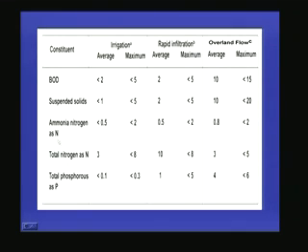The reason is, if you put wastewater with high pollutant concentration, what will happen? The land will not be able to take care of the pollutants properly. So some of the pollutant will be left over after the land treatment, and it will be percolating and going and meeting the groundwater. So whatever is the existing groundwater, that also will be getting contaminated.